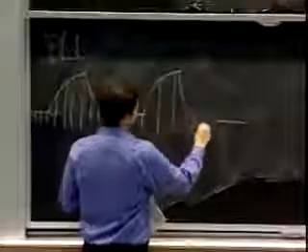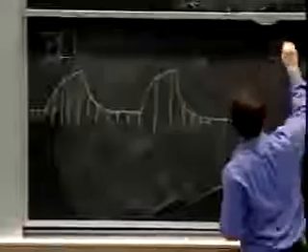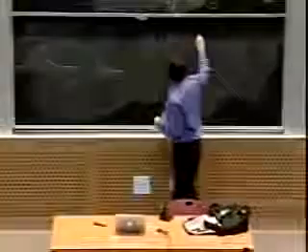Suppose we have our signal like this, okay? A simple way to implement a phase lock loop is to take this signal and to sample it not once per clock period, but some multiple number of times per clock period. We call this oversampling. We might do, for example, 8 times oversampling on this. What that means is if we were perfectly lined up in time on this oversampled signal and we were encoding a 1 as a high and a 0 as a low, then what we would see is alternating sequences of 8 zeros and 8 ones, right?